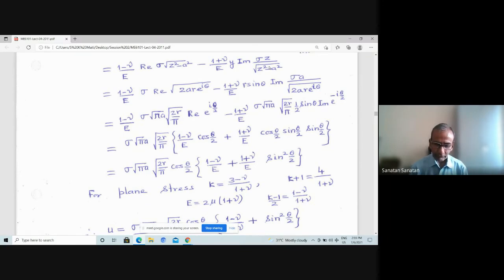Yes, please. We have talked about the solution for stresses for problems in 2 dimensions. Then we wrote the equilibrium equation. Then we noted the problem is statically indeterminate. Then we overcame the static indeterminacy by bringing in compatibility conditions, and these compatibility conditions were finally given in terms of displacements. In the case of rigid body problems, the beam problems in strength of materials, there also you have compatibility equations, but there they apply to the whole body, whereas in this case it is a compatibility equation at a point.